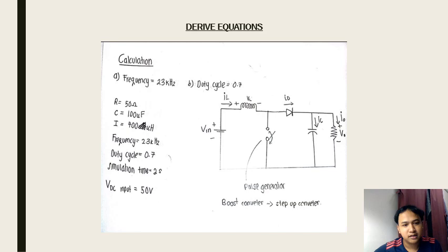We use resistance 50 ohm, capacitor 100 microfarad, inductor 400 micro, frequency 23 kilohertz, duty cycle 0.7, simulation time 2 seconds, and VDC input is 50 volt.